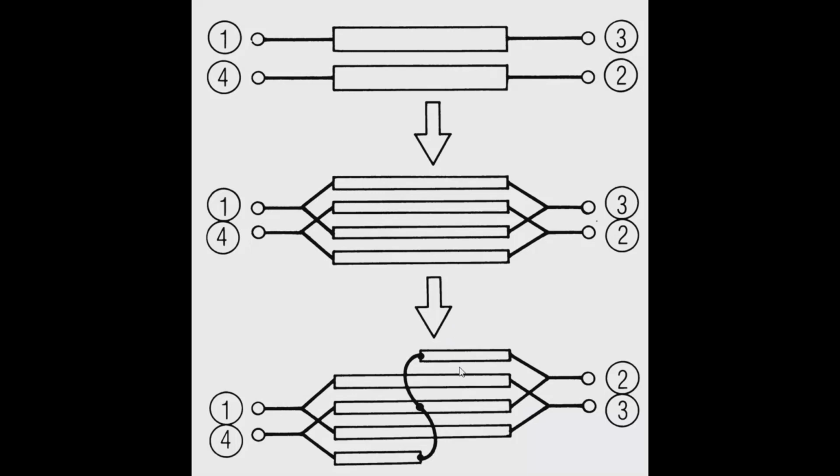And the gaps also become very narrow. So it's very likely that these are going to be fairly long, since they're a quarter wavelength long, and they're going to be very thin. So the length of these bond wires is really not very great. And of course that means the parasitics they introduce are also not going to be very great.